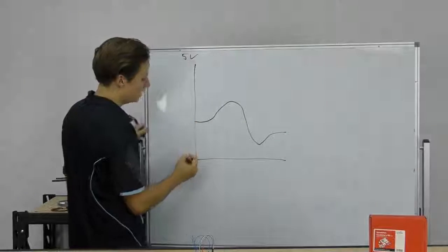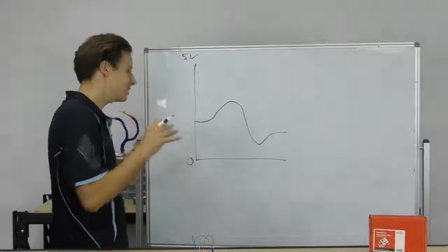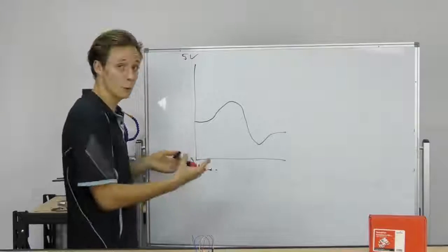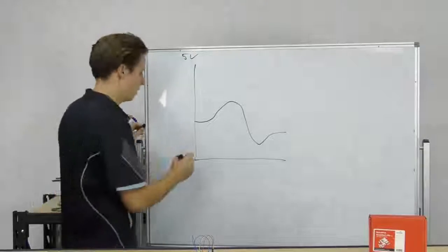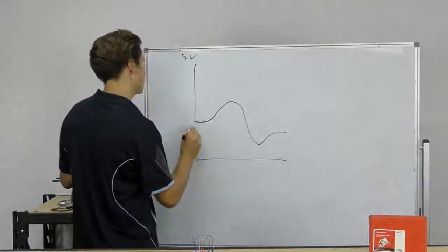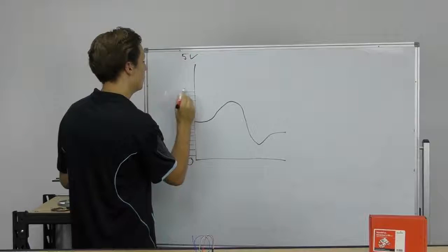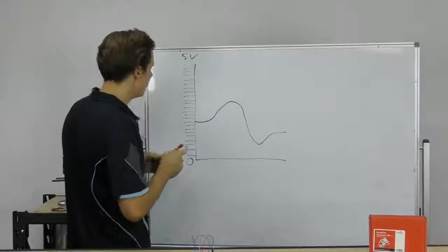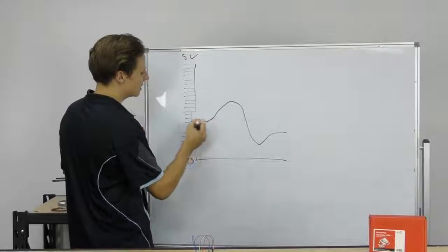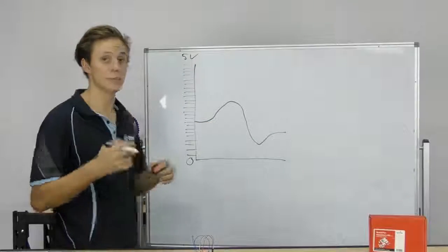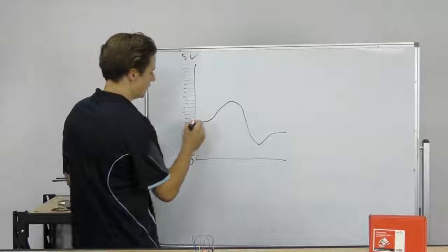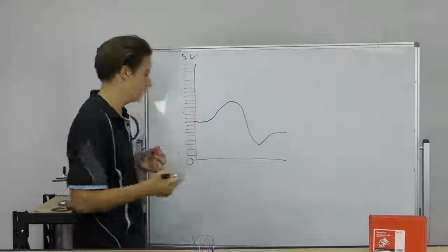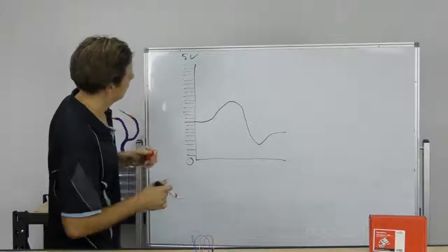Now what happens is that, so we said 10 bits, that's 1024 possible values ranging between 0 index, and 1023. So it breaks it up into all of these increments. There was way more than I can draw on this graph, but you get the idea. Now it would break this up and find what this signal is equal to at a set rate, which is the frequency that it's sampling at. So let's say here it samples it and it says, yeah, it's at that particular value. It might assign that to, let's say, maybe 400.